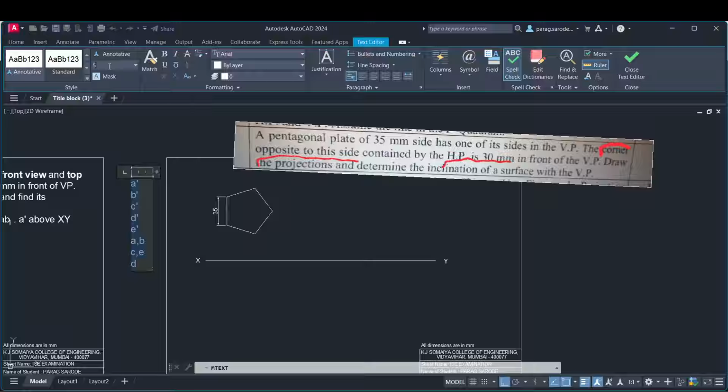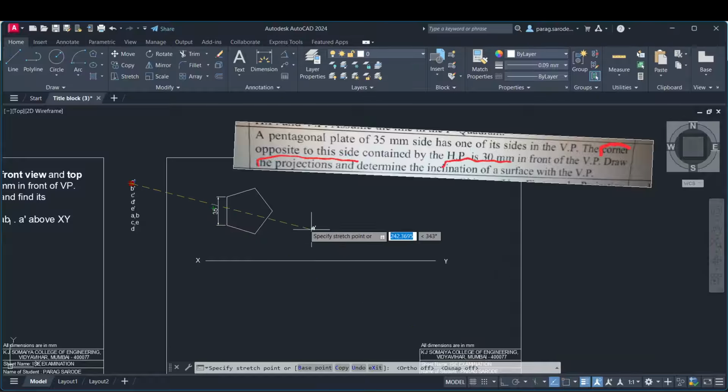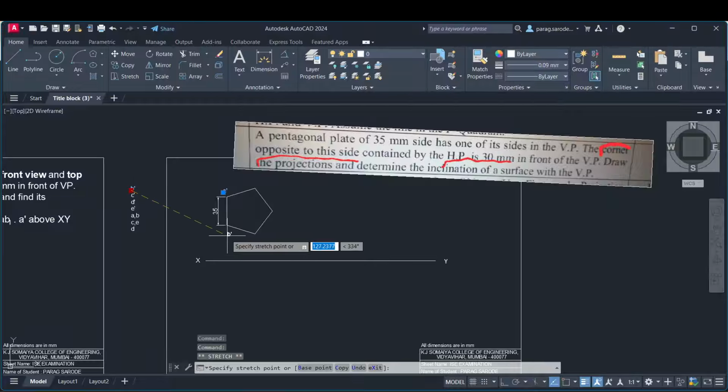And then we select all and make the size smaller in this way, right? And then we select all annotations and we select the explode and we move it. While moving, you have to switch off the ortho and prefer to switch off the O snap in this way. Okay. Again, it's a matter of practice whether you are able to do it. Most of your time will get wasted in moving these annotations rather than drawing the diagram.